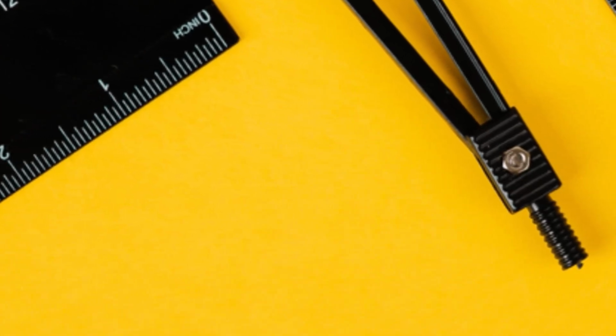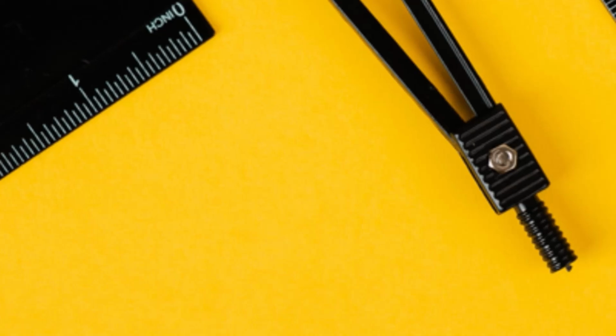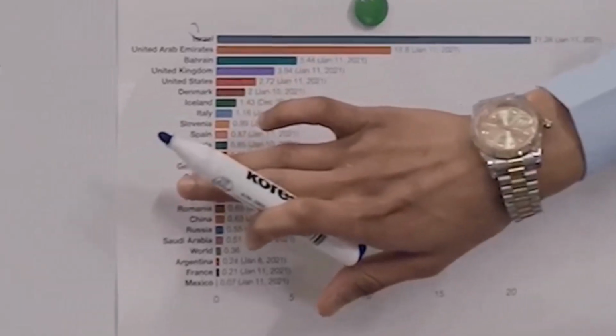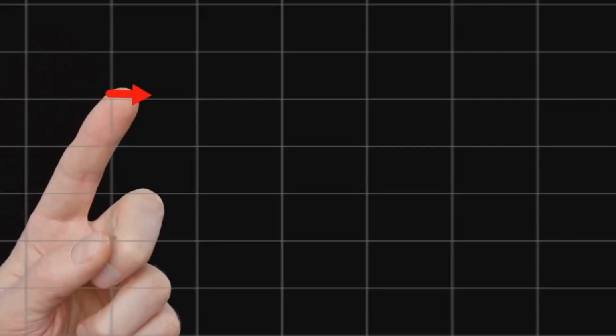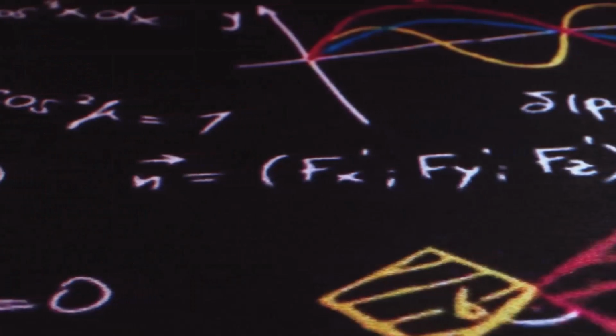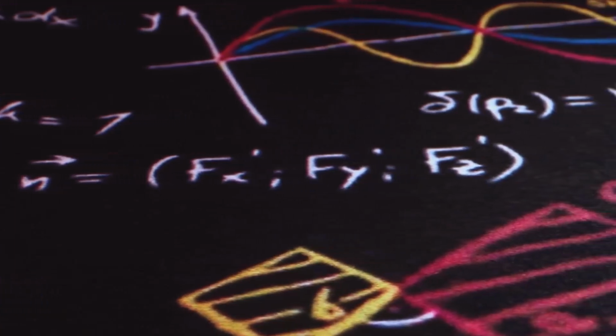The real part tells you how far to go along the horizontal axis, left or right, and the imaginary part tells you how far to go along the vertical axis, up or down. This two-part system is a perfect match for our phasor arrows. The horizontal position corresponds to the real part of the complex number, and the vertical position corresponds to the imaginary part. Every phasor can be described by a unique complex number.